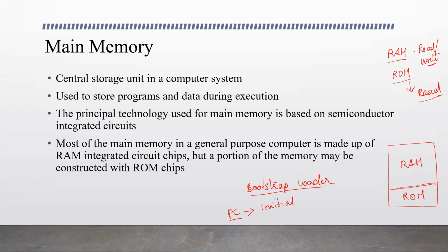So this is the initial program, and it consists of standard instructions that do not require any change. It is a standard routine that is executed every time the computer is switched on. So this program is stored in ROM. It does not require any change. Such programs, the bootstrap loader program and other programs that do not require any change, are stored in read-only memory, and the programs that require changes, that may need to be changed by performing a write operation, are stored in random access memory or read-write memory.